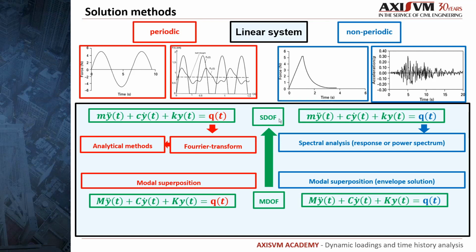Modal superposition gives us an approximate solution, since the accuracy depends on the number of natural vibration modes used for the analysis. Moreover, spectral analysis provides conservative envelope results, since the analysis is done in the frequency domain and therefore only peak results are superposed.